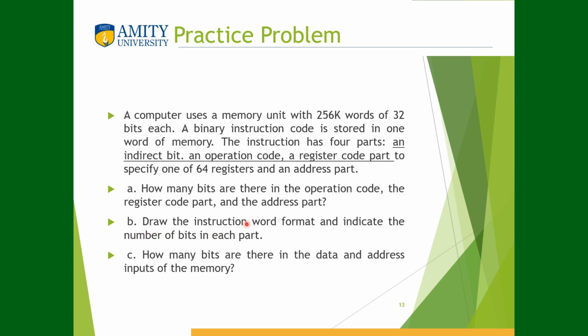In B we have to draw the instruction word format, and we have to show the number of bits in each part. And in part C we'll be determining how many bits are there in the data and address inputs of the memory.